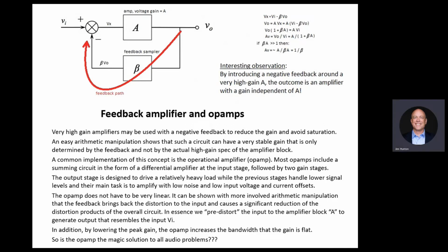It's really determined by how you construct your feedback. If you have low gain in A, now it's different. Now you have to do math. So in many senses, an operational amplifier is great. You basically say, I have a device with a lot of gain. I put a few resistors around it and it fixes it to a specific gain. Okay, and I'm done. It's very nice from that point of view.